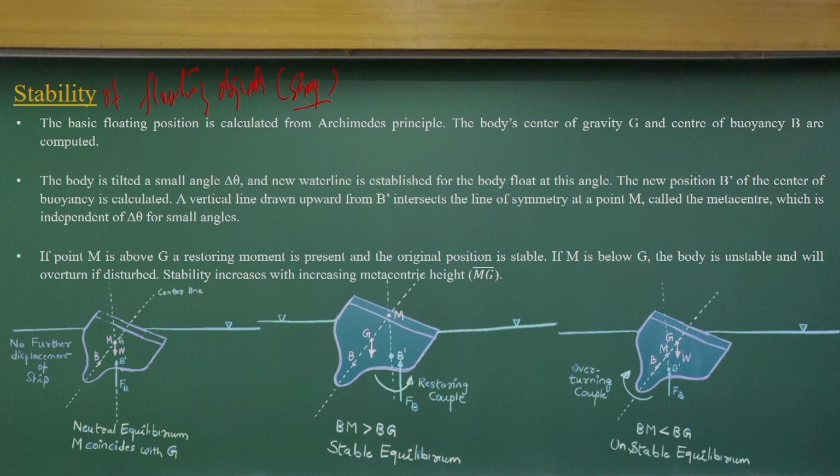Because of that, we will have stability problems. If I make a small disturbance or slightly rotate a floating object, what happens? Does it come back to its original position? If it comes back to the original condition, then I will say it is stable. It has stability; it can come back. Any small change will not change the stability of the floating object. It will come back to the original position. But on the other hand, in unstable equilibrium, if there is a slight tilting of the floating object, it generates a large rocking and finally capsizes, then we say it is unstable equilibrium.